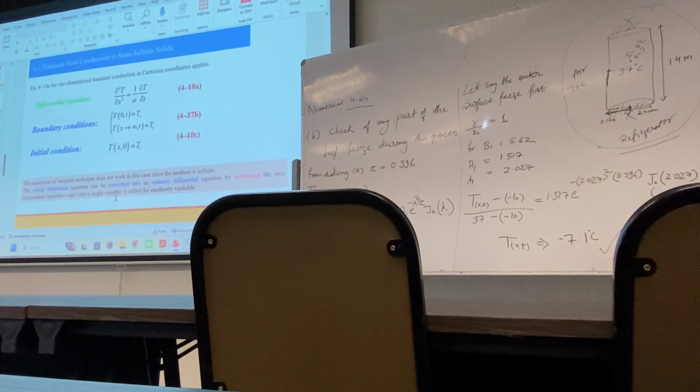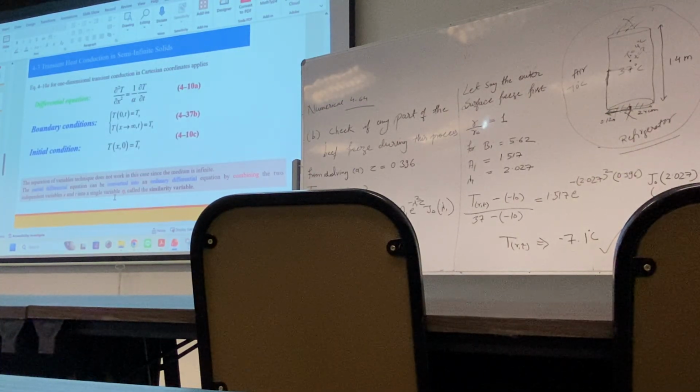Okay. So like in 4.2, you had some non-dimensionalized values like tau, and non-dimensionalized temperature like theta. In semi-infinite solid as well, you have some non-dimensionalized quantities. Okay, first one is eta, which represents x and t. X is the distance until the heat transfer is happening, your heat is penetrating, and small t is the time.